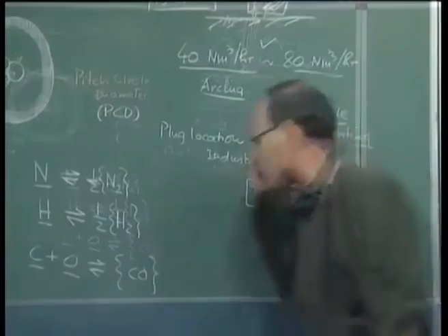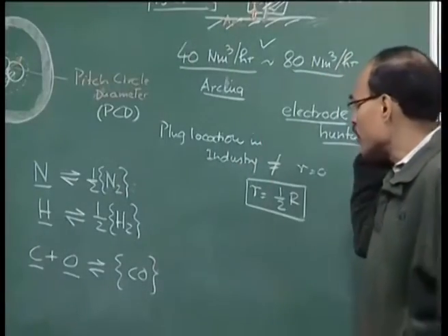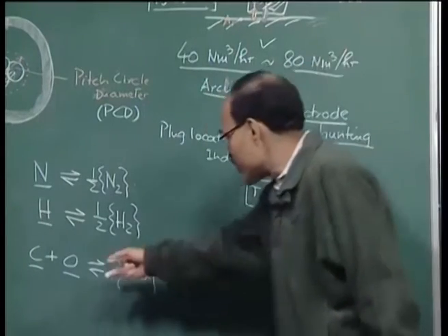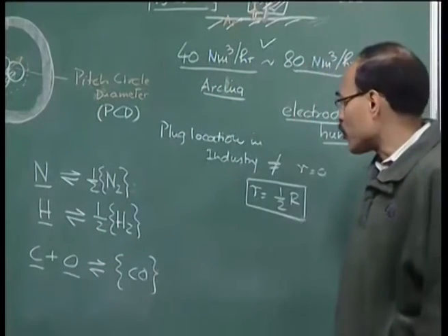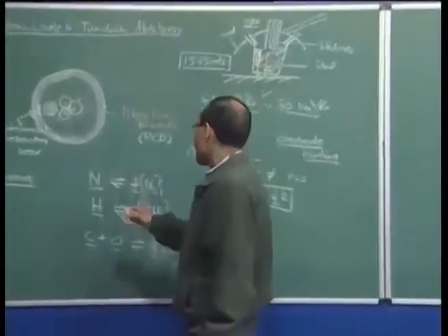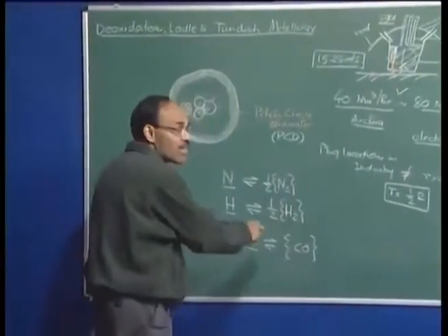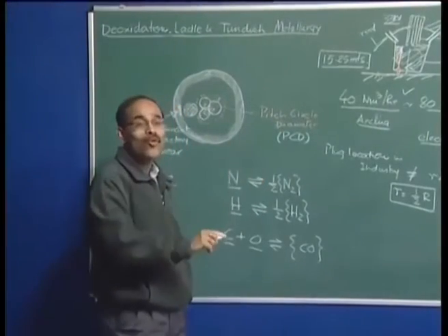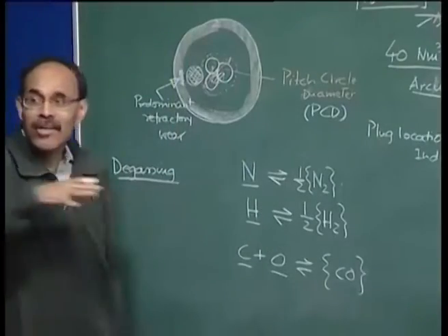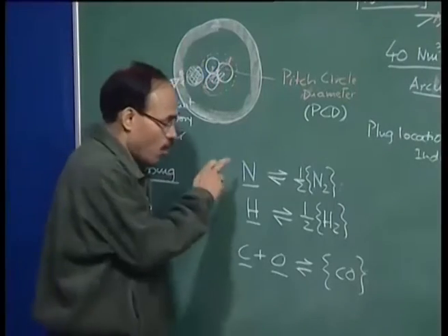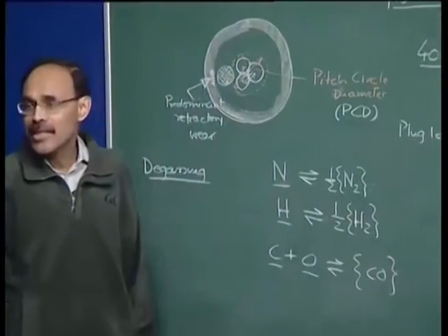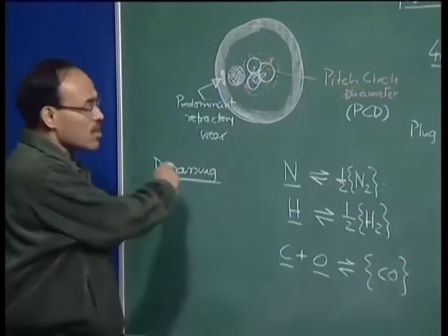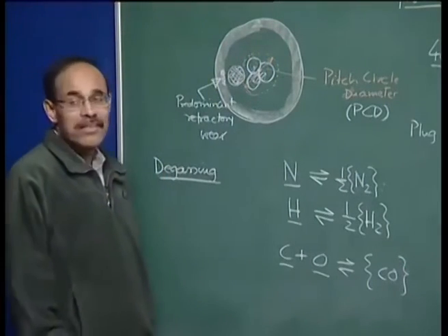By continuously removing hydrogen from the system, we will be able to facilitate the metal to lose hydrogen, and the same is true also with carbon monoxide. So, all these gas forming reactions, the 3 reactions I have enumerated here, are going to have a greater tendency to move in the forward direction from left to right under reduced pressure, and that is why we carry out the degassing operation in steel making under reduced pressure.